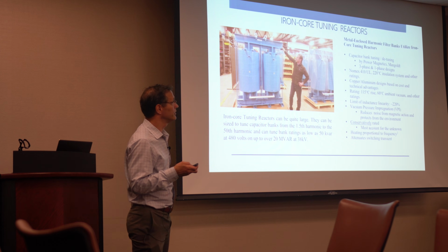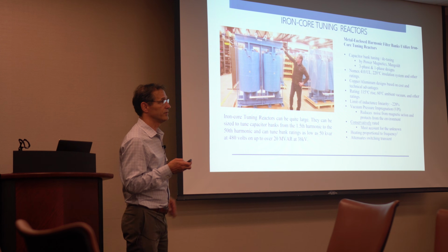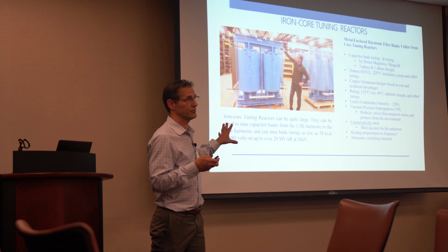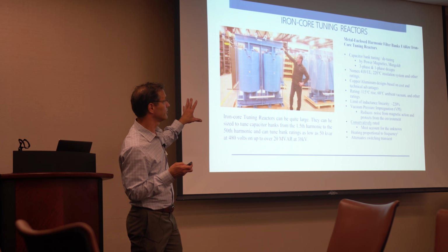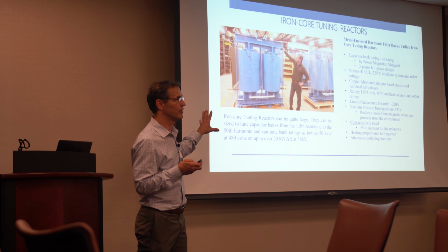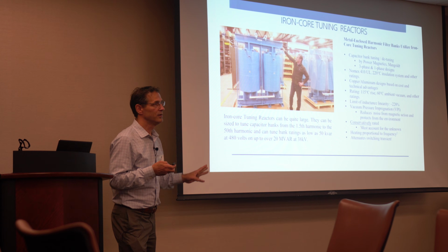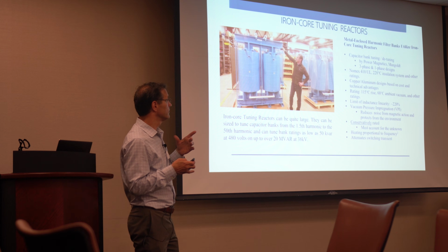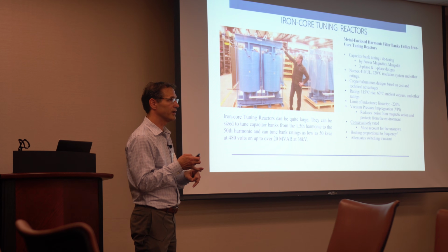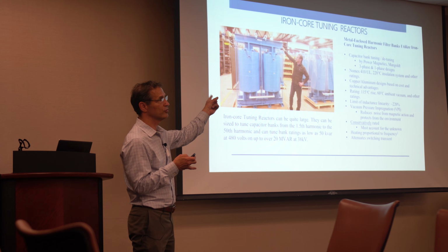So we have a design philosophy that is to overrate those reactors, because when they are not designed properly, they throw out a ton of heat, and they vibrate, they make a lot of noise. So we have a philosophy that for the fundamental current rating of the bank, we take that reactor and we multiply the current by 1.5.